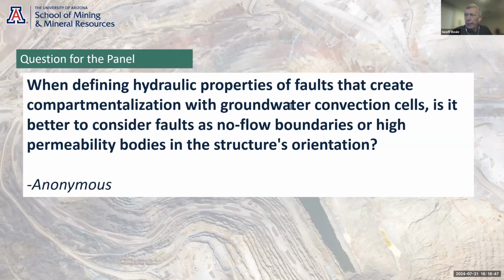2 is they potentially have gouge. 3 is that they create altered rock and softer rock around the fault, so the fractures heal. And fourthly, you often get subparallel microfractures either side of the fault. So the water wants to go perpendicular to and not cross the fault. So there's those four reasons which mean that the majority of faults create barriers across their strike.